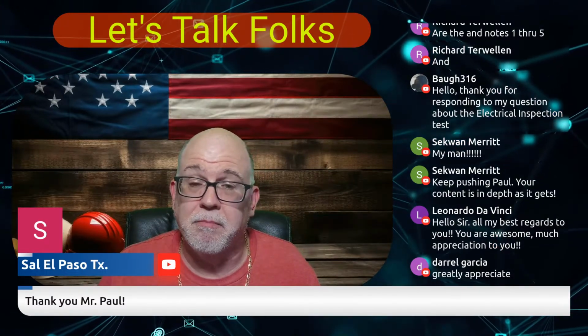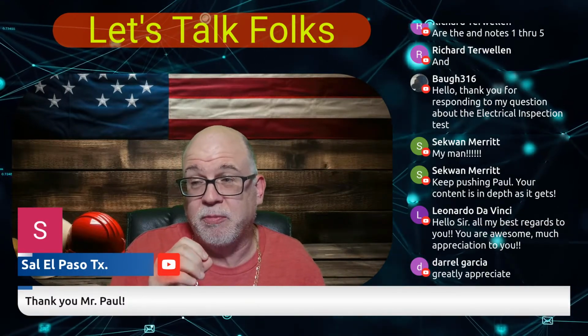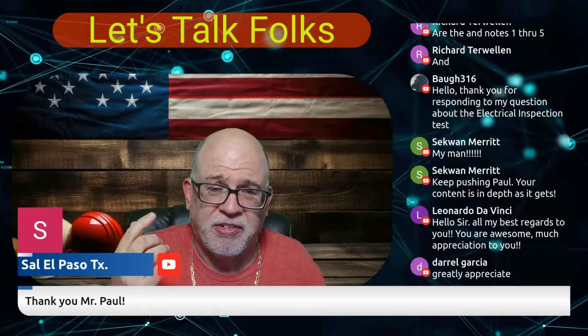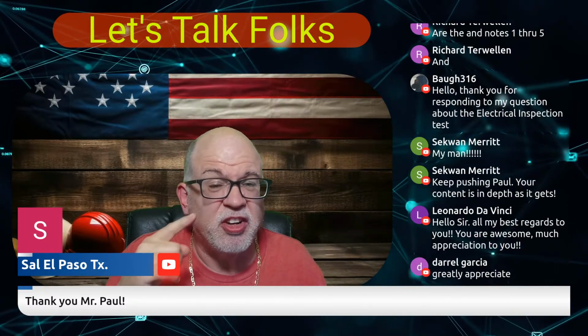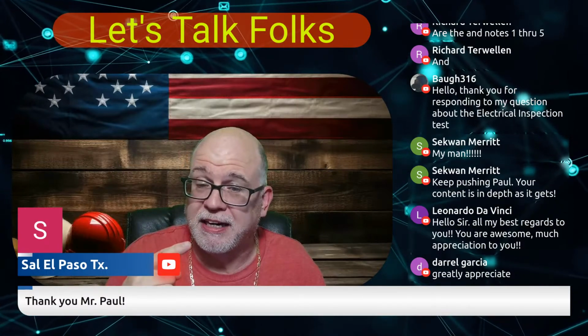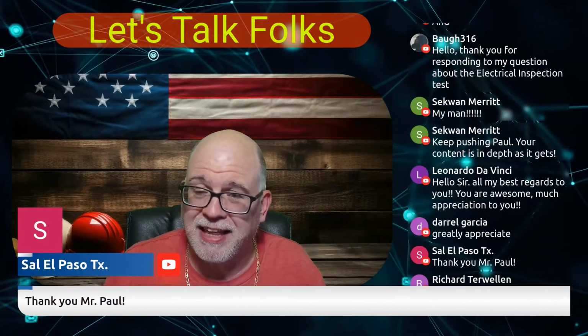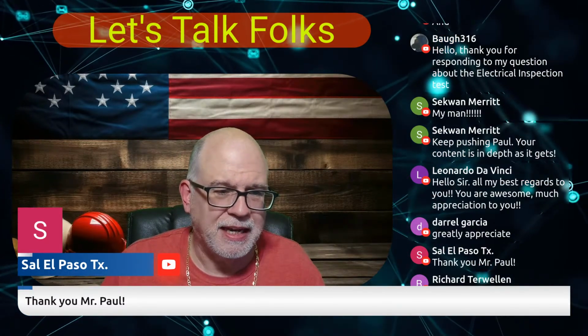That's talking about motor branch circuits and not the normal, whereas people know that you just do 125% of the FLC. But we want to make sure that you understand that if there is an adjustment or correction due to ambient temperature or more than 3 current-carrying conductors, you've got to take that into consideration as well. So we're going to cover that today. So make sure you check that out, okay?